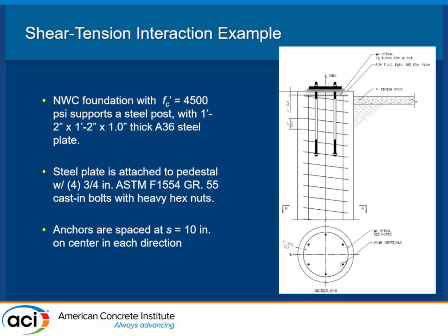And then for shear, the question was already asked, can I use my ties? Absolutely. Depending on how these plates are, or if this bolt is welded, or you put washers on top and welded washers, whatever, you could say that your load is from back here or it's from here, and I could just put three ties at top or two ties at top, three inches on center or whatever. It's probably enough to get you out of the problem, unless it's just a crazy load, in which case I didn't have to do any of Chapter 17. I got out of it right there.